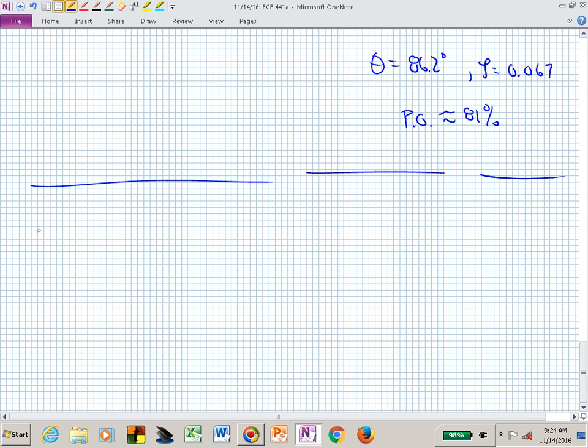Let's now think about speeding up the response. We are wanting to change dramatically the root locus shape. We don't like this original shape that just goes up and makes the system shake more, faster, without changing the settling time. So if we want to change the shape of the root locus or speed up the response, speeding up the response means bend that root locus over. What kind of controller is possible that we already talked about? A phase lead.